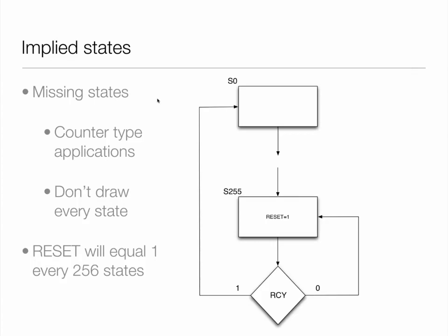What we're doing here is we're modeling what we want to implement. And we're doing it with state machines, which, although it sounds like I'm a complete state machine convert, it's not like that, actually. They are great for working out what it is you want to do and all the timing. When it comes to actual synthesis, you may do things differently, right? And here's an example of that.